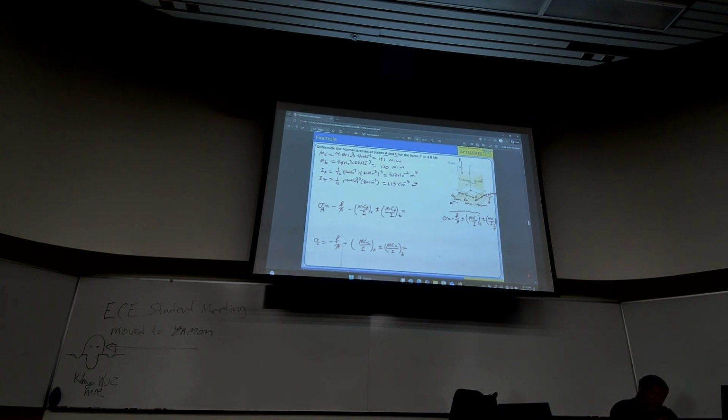All right, point A, and look at bending about Z. Bending to the left, is A being pulled or pushed? Only look at Mz. You just look here, because the force is slightly to the left of Z, actually by 25 millimeters, right?